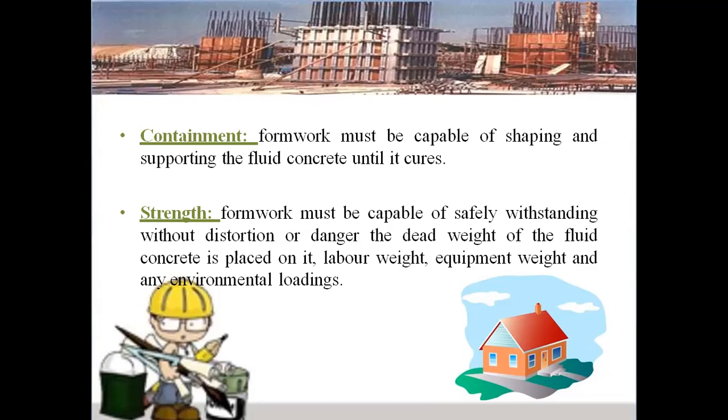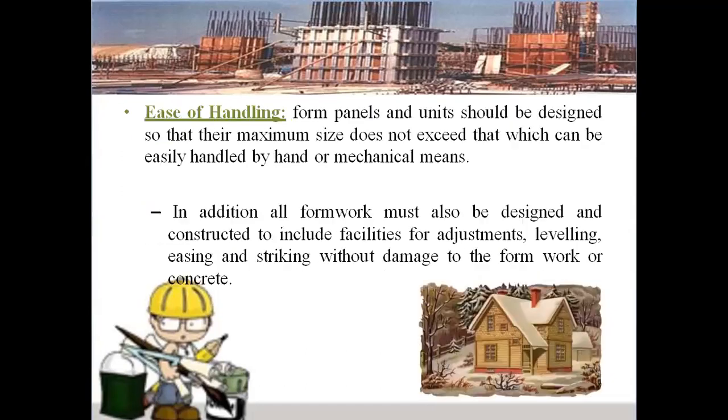So the formwork must bear the dead weight of the fluid concrete placed on it, the labor weight, the equipment weight, and any environmental loads applied on it. So the formwork must be strengthened to withstand all these loads.